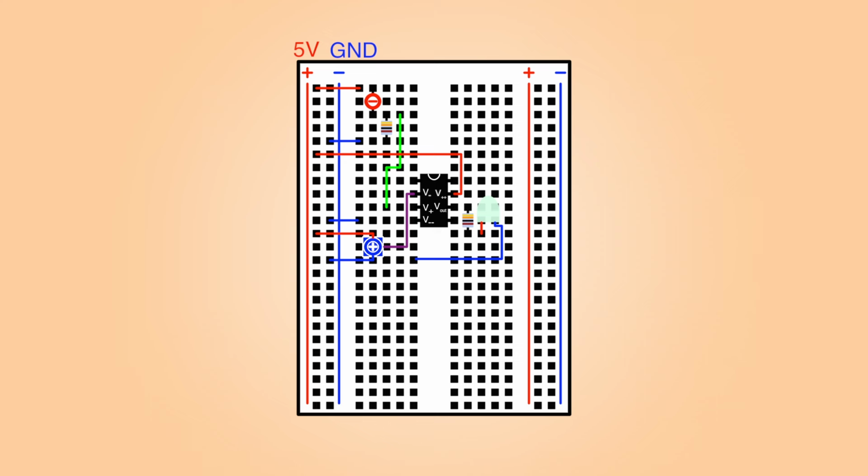We set the potentiometer such that when the photoresistor is in bright light, in other words above the threshold, the non-inverting terminal is at a higher voltage than the reference. This causes the op-amp to amplify the now positive difference between the input voltages. Because the op-amp's output voltage range is limited by the power supply, the device outputs V++, the positive rail voltage of 5 volts, illuminating the LED. In this way, an op-amp without feedback can be made to operate as a comparator.